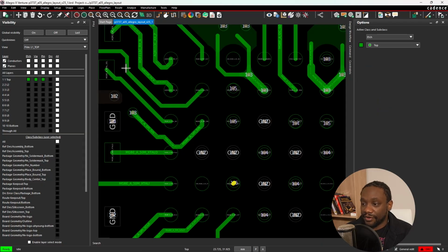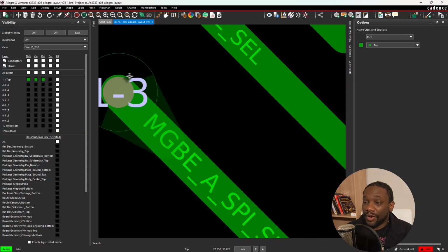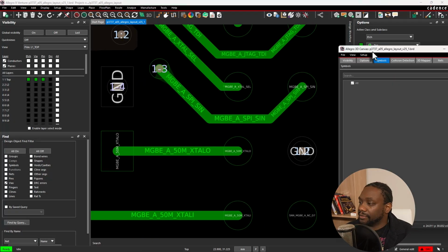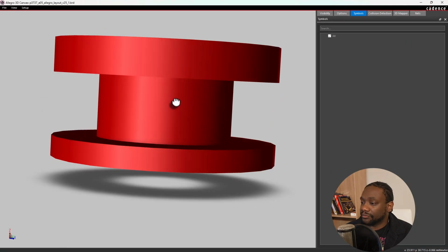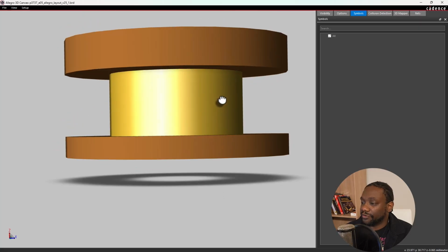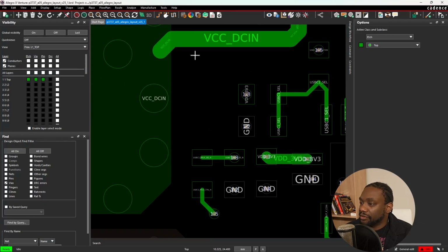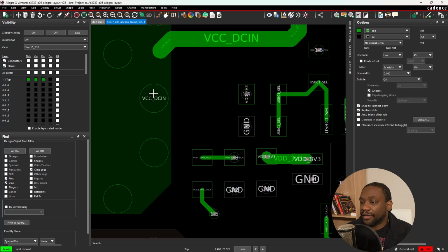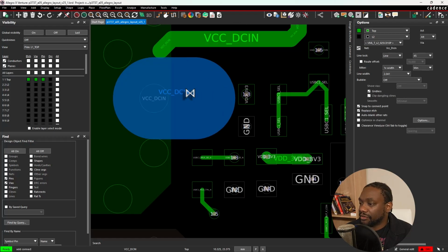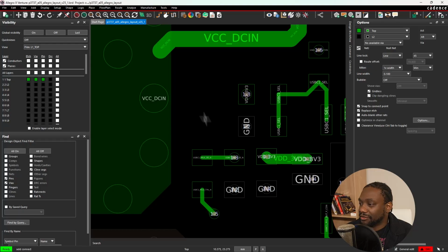Here we've got the layer 1 to 3 via. And when I do a 3D view of this via by clicking on it, it shows up like this. This is what it looks like in the 3D view. Okay. So yeah, that's all you have to do. Just if you want to use your via, start routing, start your trace. Okay, that's a little large. 1 second.